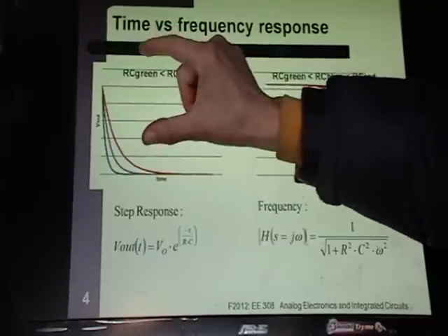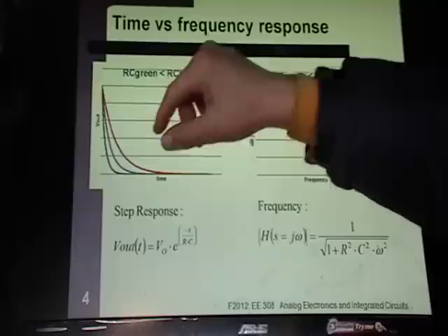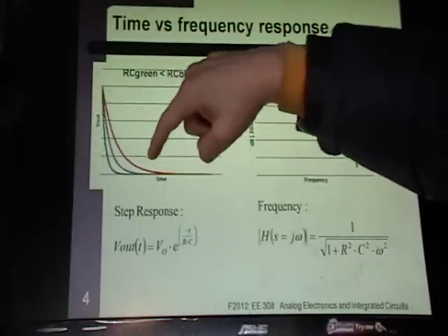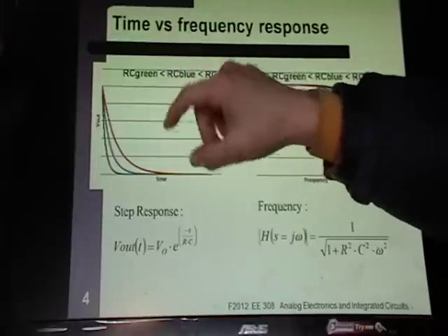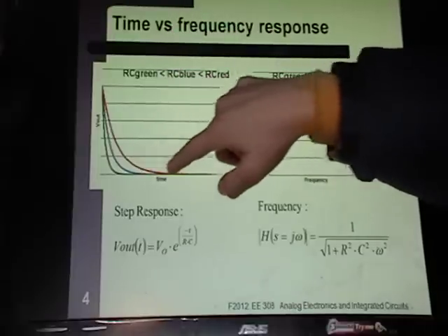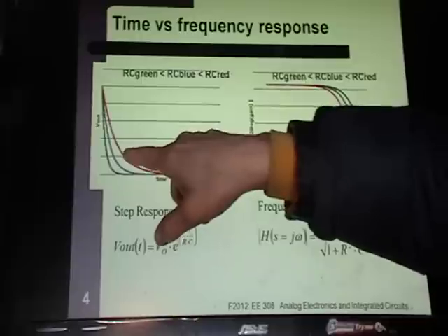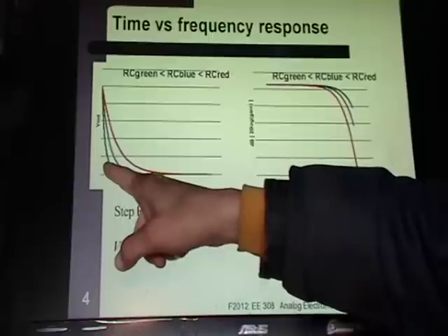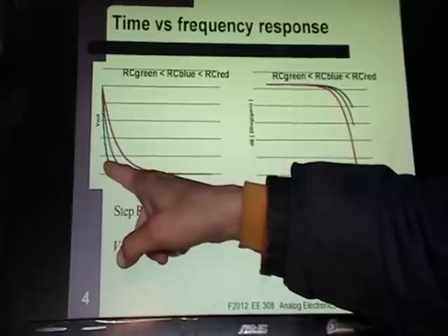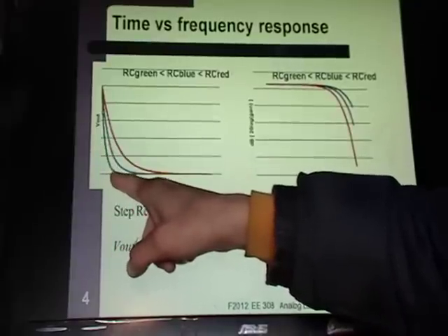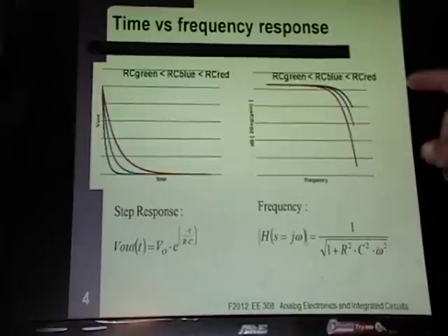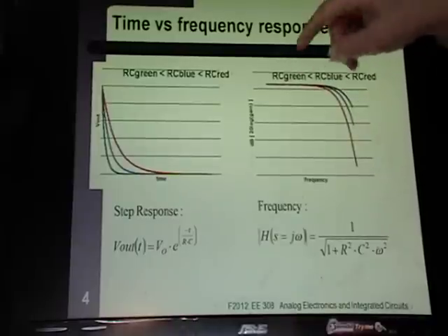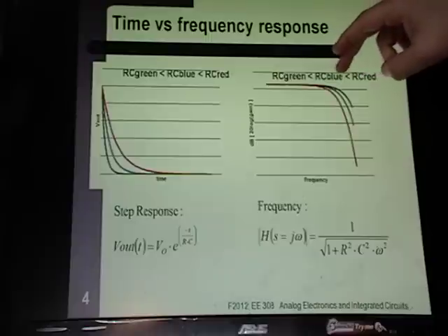But then as the voltage across the resistor gets smaller and smaller, the current drops, and as a result of that, the voltage drop across the capacitor slows down. If you have a big capacitor, it takes longer for it to discharge. If you have a smaller capacitor or a smaller resistor, so you get more current, it takes a short time to discharge.